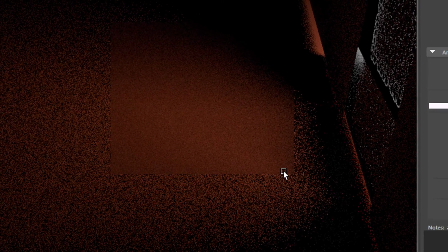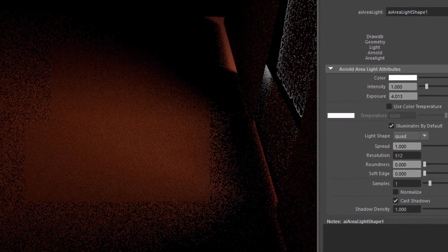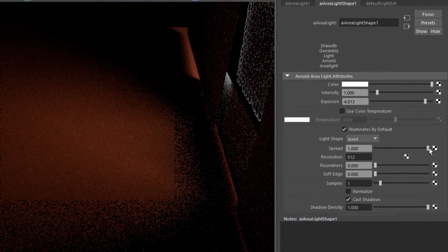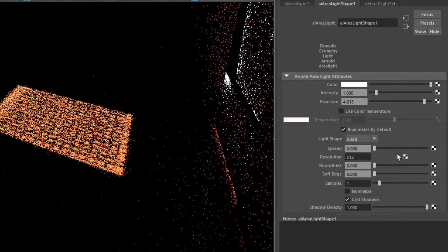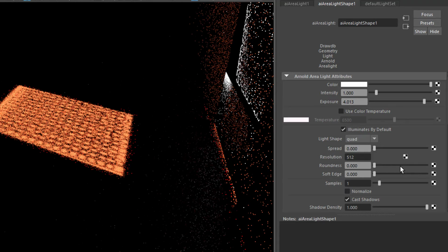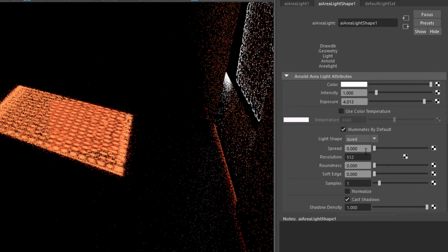Here you see because the geometry is not totally 100% intact, we have these kind of light effects here and down here. Interesting for us is this shadow, and the shadow doesn't resemble anything of the geometry of our scene and of our mesh object, and the reason is the spread. The spread is currently set to 1. If we reduce it to 0, everything will be visible on the ground now. And actually this is too much and too rough, I guess.